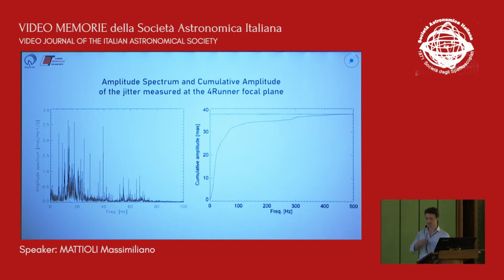But we also know, thanks to Guido, that the jitter at the camera is way less than the one we used in our simulation, which is good. If we want to correct most of the energy of the jitter, we have to go up to 1 kilohertz, which leads to a loop period of about 1 millisecond.